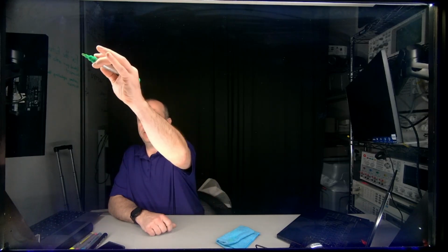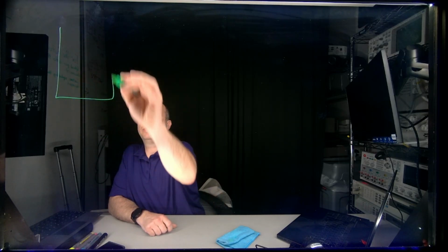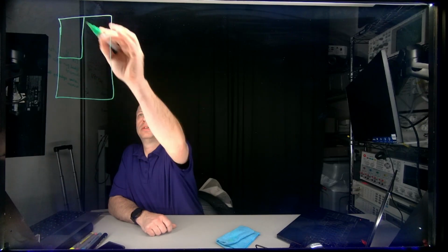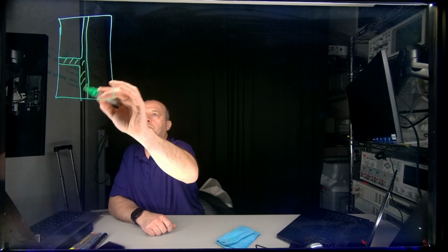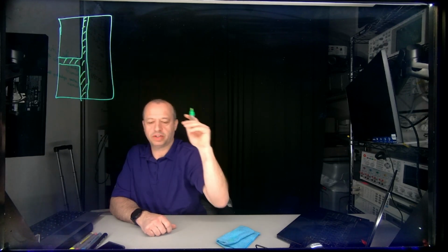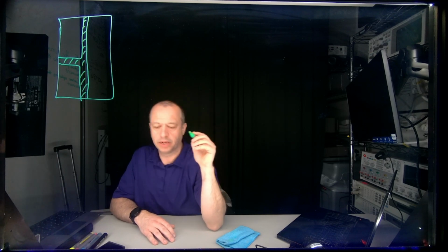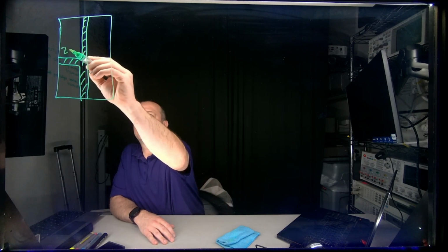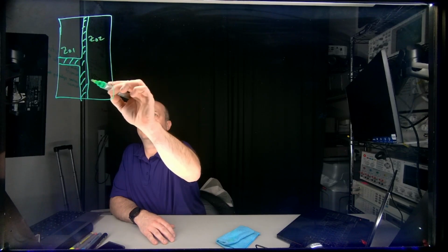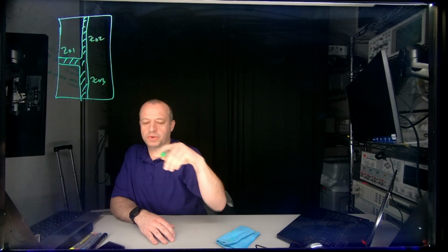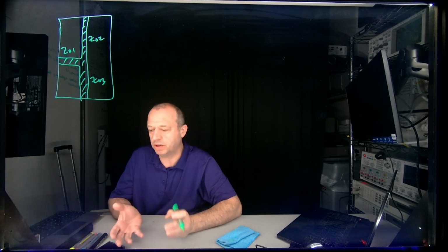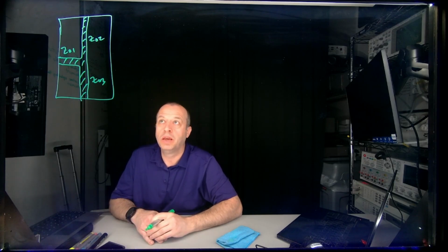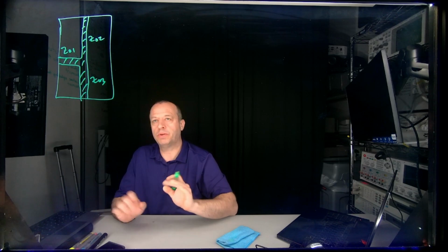The next one we will talk about is a split trace. And you can look at the figure for better drawings. My drawings are probably not that great. And we're just going to consider this Z01, Z02, Z03, meaning they are separate impedances on each trace. Most of the time, this 2 and 3 will be identical because most of the time you want to split power between these two and you want to split power equally, but not always the case.